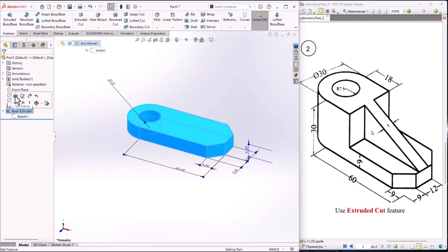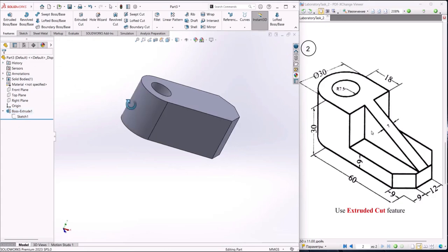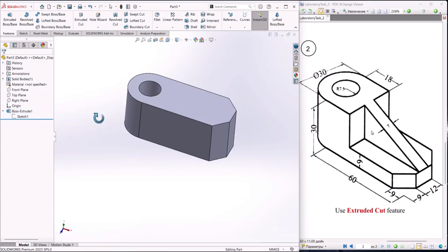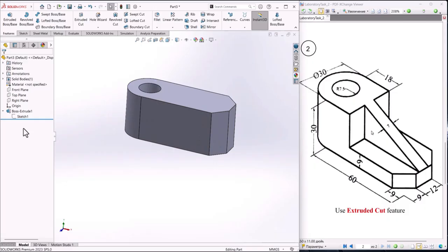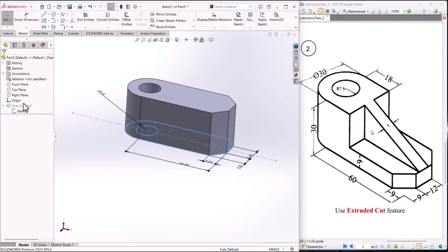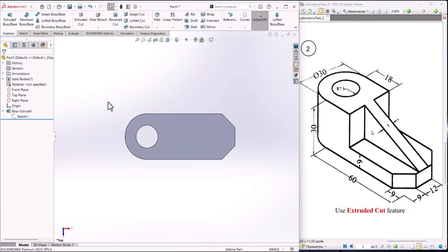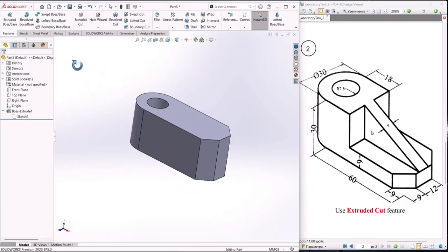You will see in this frame the commands. So the first command is edit feature. You can go to the feature and then change this value to 30 and click OK. So now it becomes 30 millimeter height. But if you want to change the base shape, just select the sketch and then go to the first one, edit sketch, and you can change these values, or you can draw any other thing, and then that will be extruded. Okay, so now I want to cut this area,